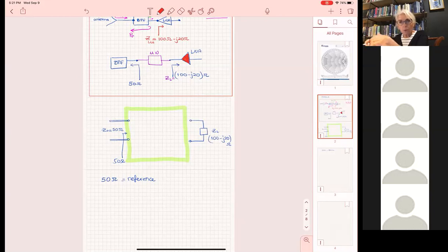And the input will be somewhere where the LNA stops. I mean, it may have a capacitor in there, who knows, may have other things. So we don't wanna bring our stub too close to the LNA, because I don't know what I may mess up there. And you can never really be that close because there is always some spacing. While the solution that your colleague mentioned is absolutely correct on paper, let me just do that for a moment on paper, because it is correct.